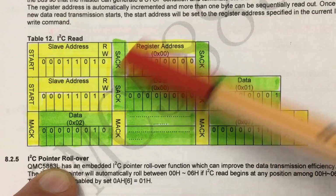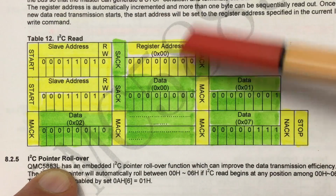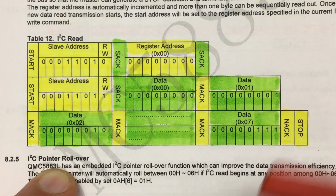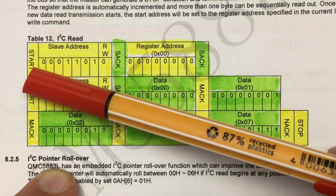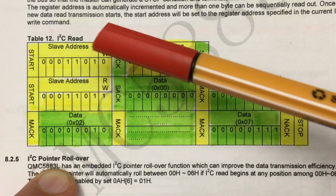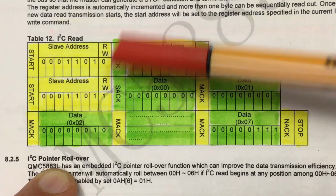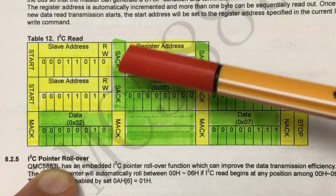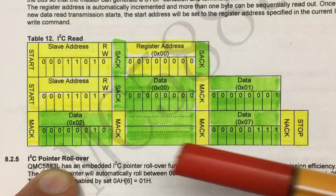And I've hand colorized it here for your convenience. So yellow is stuff transmitted by the master and green is stuff transmitted by the slave. The master starts by transmitting start and then the slave address followed by a read-write bit set to 0, meaning we want to write some data to the slave. And the slave acknowledges that, and the master writes the register address it wants to read to the slave. That's also acknowledged by the slave.